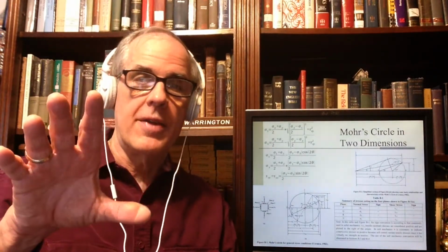Principal stresses are if you keep rotating it, and I'll talk about the convenient axis. If you rotate an axis, there's 2 points which are important. As long as I keep rotating this thing, even though static equilibrium does not change, the values of the 2 normal stresses and the shear stresses will change. And there are 2 angles at which we are of special interest.